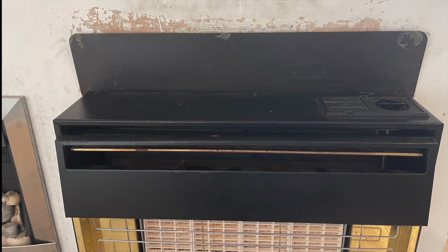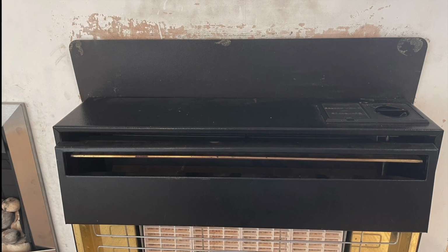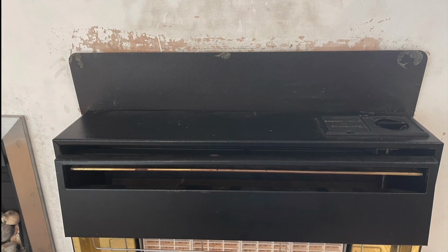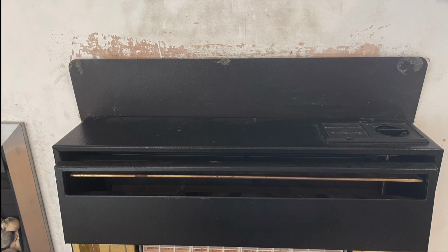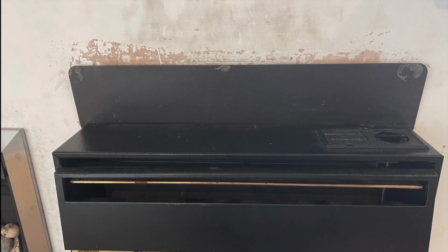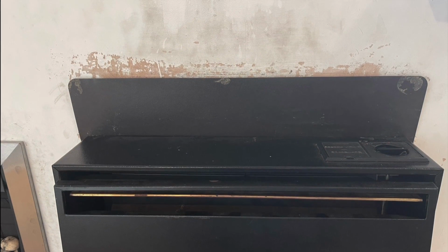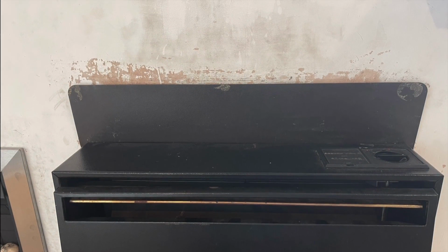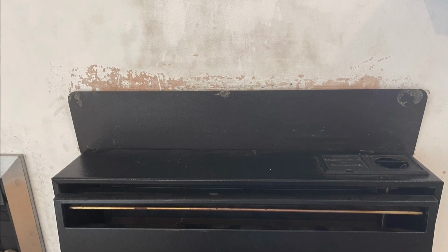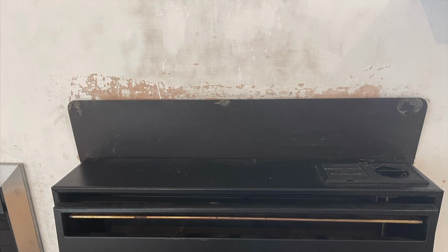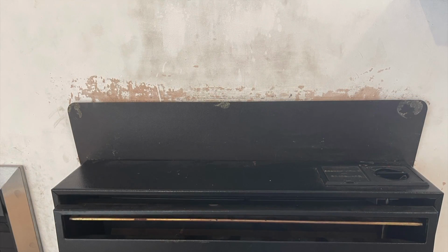Now this next scenario represents you going to do a service of a new condensing boiler. And because you go through into the living room, and according to IGEM G11 Appendix 5, you have actually encountered this gas appliance, you see this staining above the top of this radiant gas fire. So, what is this staining, and what would you classify this situation as? Remember, you're not there to work on this fire, you're there to work on the boiler.